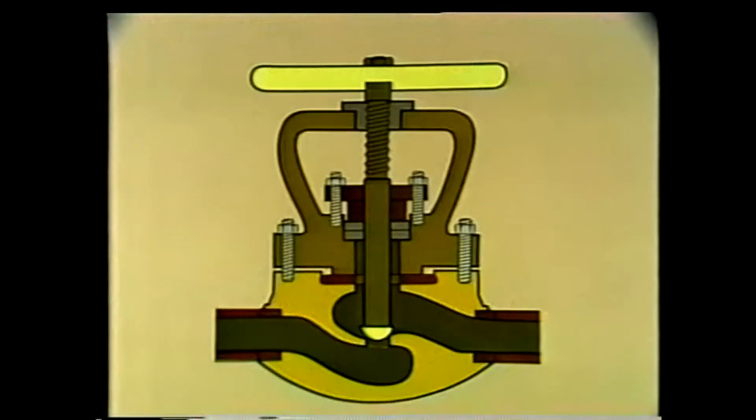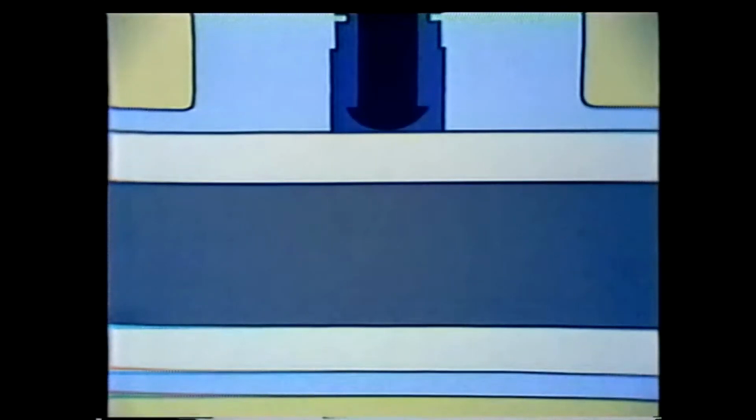The pinch valve has good throttling characteristics due to the smooth, straight flow path through it. Now, in contrast, on a standard valve, the path of flow is changed as it passes through the valve body. This causes a pressure drop to occur. However, the flow passes straight through the pinch valve, causing little or no pressure drop.